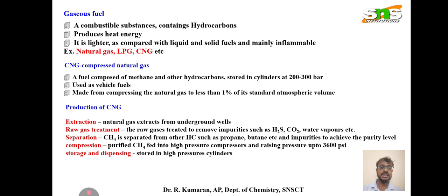After that it is compressed. Purified methane is fed into high pressure compressors, raising the pressure up to 3600 psi, which is the desirable value. After that it is stored and dispensed in very high pressure cylinders. These are all the steps in the production of CNG, the working mechanism of CNG.